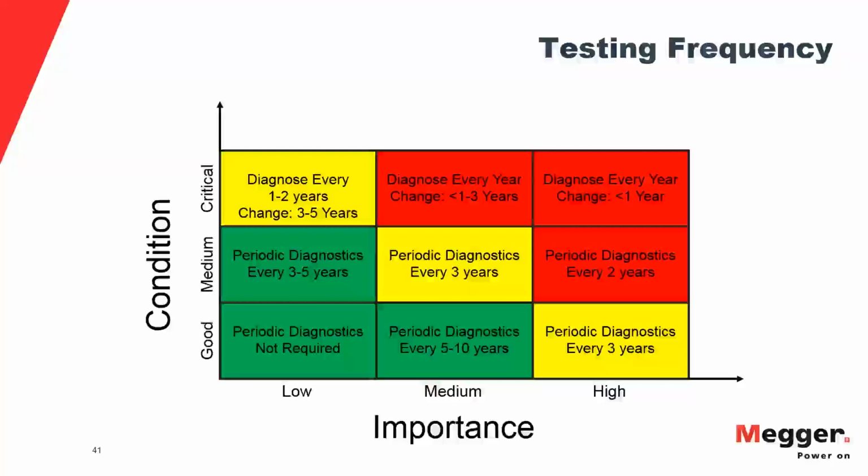And for offline testing, you integrate the whole signal from the low kilohertz to the high megahertz, and that gives you the full charge, like the apparent charge that you are actually getting. And of course, if there is an interference in these frequency bands, then you will see this. But for sure, not, let's say, audio frequencies like our ear or whatever, that's typically too low.